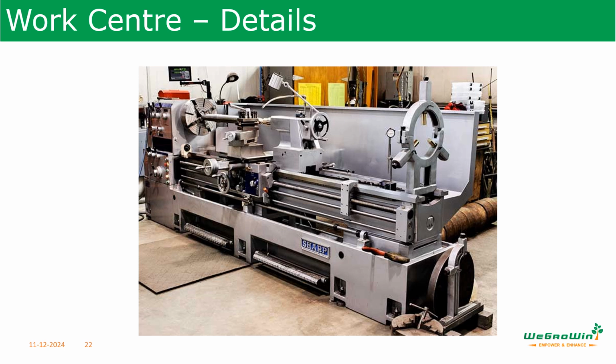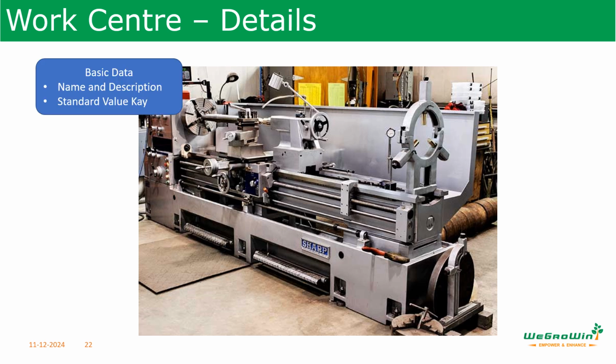The data on the work center are defined function-wise. So there is a basic data screen. Here the standard value key is defined. Standard value key defines one or more standard value parameters like setup time, labor time. Those things are defined in the basic data view. In addition to this, we have name, description, who is responsible for the work center.